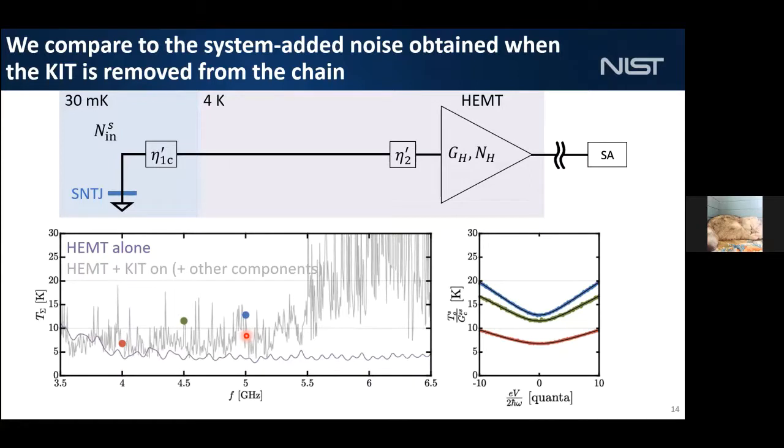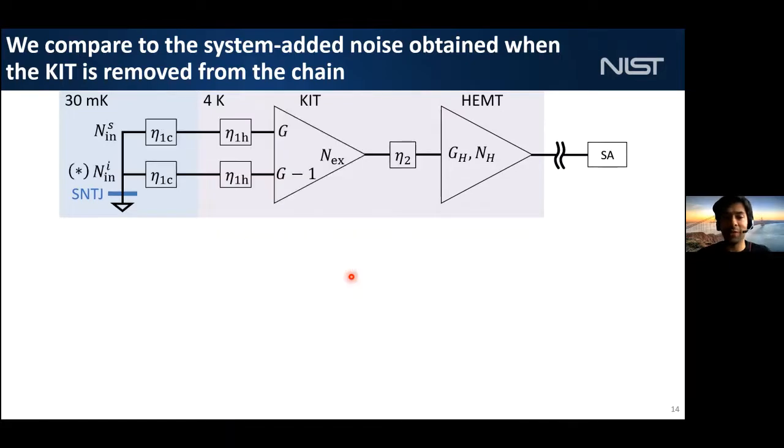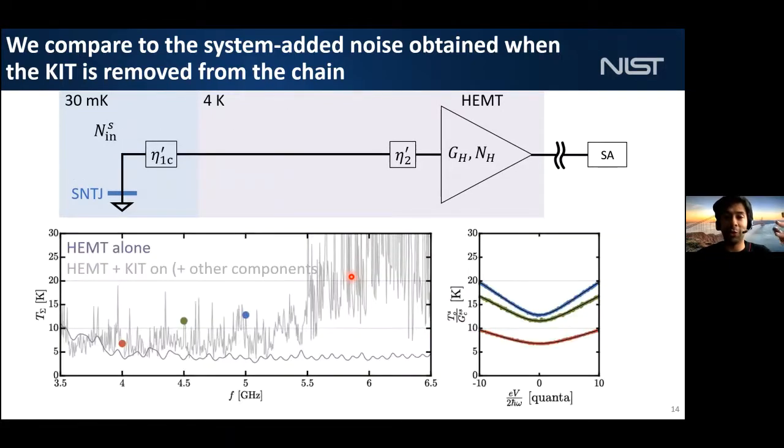Yeah, I think I have a little bit of a related question. Maybe I could take it as the last. I think I totally understand your point and your error budget. If all these connectors were lossless, you could have the connectors at a physical temperature and the modes at a different one. Maybe that's a way to put what you're saying, that the propagating modes come from the cold stage, so they're still cold. And if you don't have attenuation, you don't have thermalization either. Exactly. That's a right point I also like to sometimes make this way.